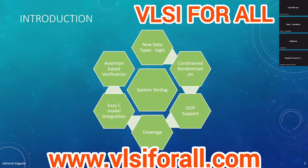So that comparison, what will you compare it with? Basically you'll create an equivalent model of that IP, maybe in C, and then you'll give that input to their design, and also to their C model, and then you'll compare the output of the C model to the output of the design. So that is one of the use cases of this C model integration.